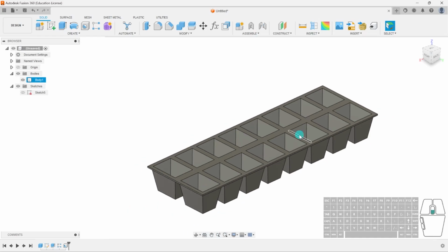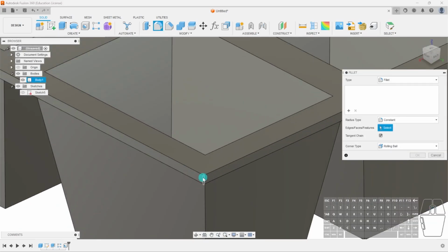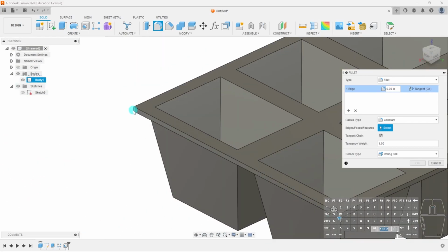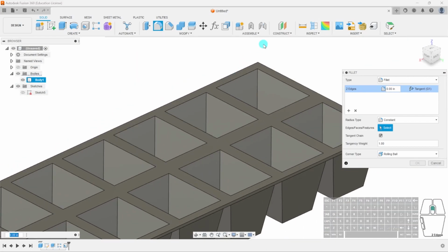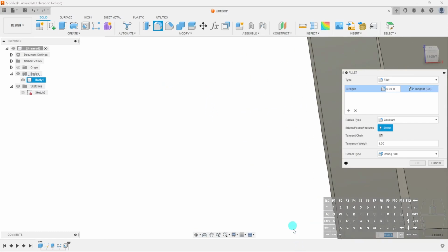But anyways, we have the main shape of our ice cube tray. That's great. What we want to do now is to make this not so sharp, so we'll fillet this with F. We'll select all 4 edges. So I'm moving the camera with middle mouse click again. You should know this by now anyways. So select that edge.